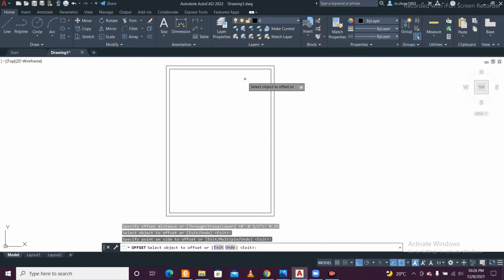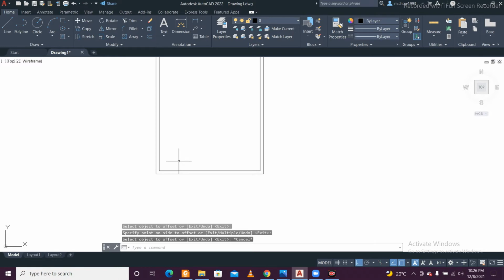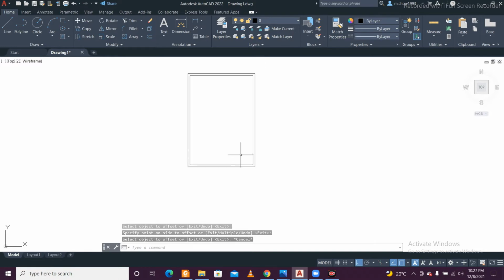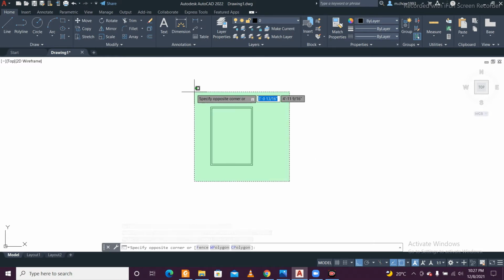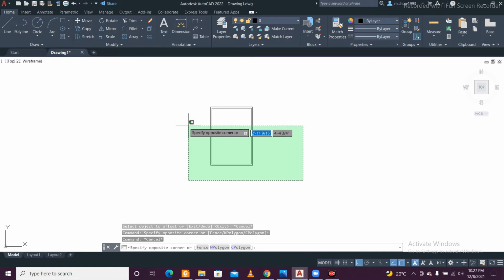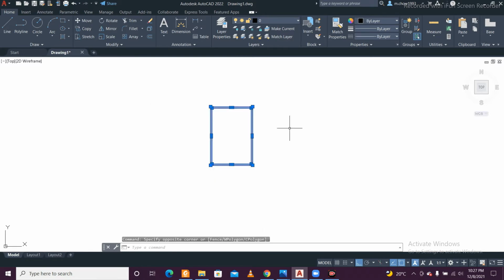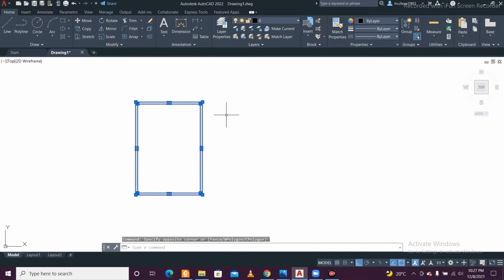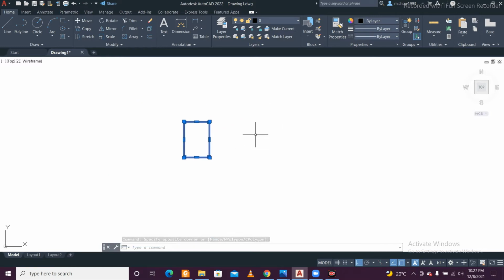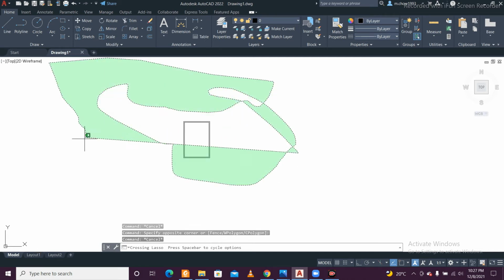Now this is okay for the inner margins, and later for the title box you can decide to keep a portion for the title box. We'll decide later. Now we can select this like this. While selecting, make sure you left click, then don't click anything, and when the entire thing is selected, left click again. This actually selects the thing. Sometimes when you are new to AutoCAD, you just click like this and like this, so you are not selecting anything.